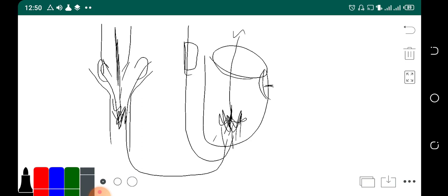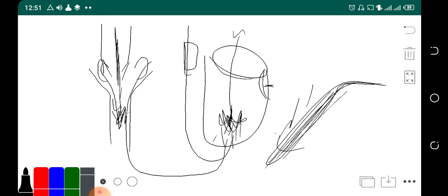Another example is the emergency air-filled slide in an airplane. The compressed air fills it, but the compressed air is not in a large enough quantity to fill the whole thing. So we also have this kind of venturi. Some compressed air will fill, and some surrounding air will also go into this place, so it fills the whole slide, air cushion, etc.